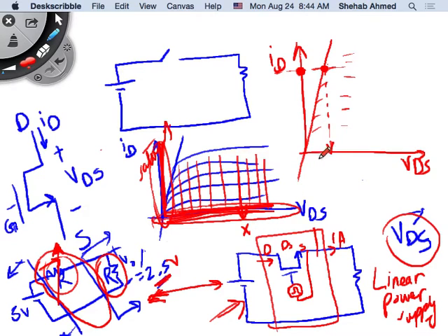A much smaller voltage, compared to operating anywhere in the linear region, right? So if I have a high current and a much smaller voltage, then the power losses across this device have decreased considerably, and the amount of losses through the circuit have decreased a lot.